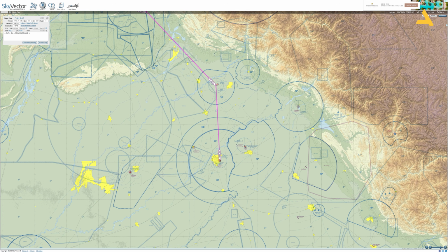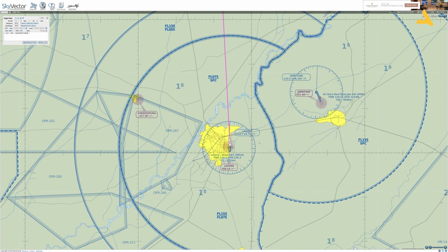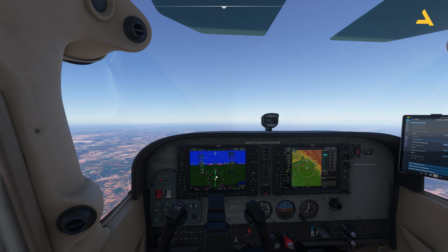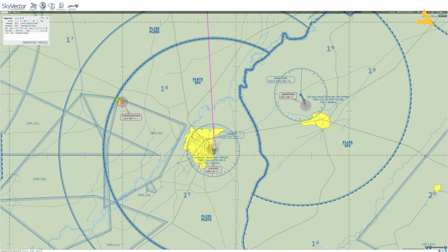Now there is something I just want to tell you, that the VOR, all these points in the compass, they are basically the radials, just like the spokes on a cycle. Just consider they are lines, and they are extended lines. So right now there is an extended line of 355 degrees, and I'm just following this line. Let me just go back and show you. So if this needle is in the middle, it means you are just following it. So right now I'm basically